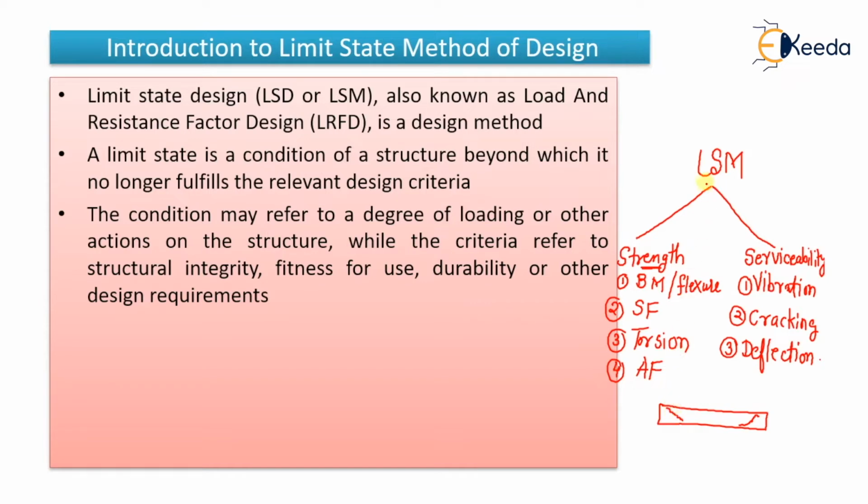But the limit state method of design says it should not only fulfill the criteria of strength but also the serviceability. This beam was designed to not only resist these various forces but also the various vibrations, cracking and deflection. It should not have any cracks, it should not have any deflection in the structure. We were expecting that, but what happened, there are certain cracks.